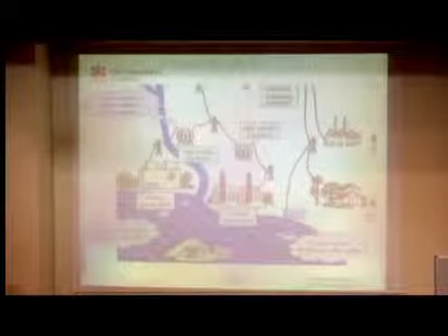So if we look at the top left of that, you can see that generator winding could be an epoxy nanocomposite, and of course the primary substation could be the same. We could on the pylons be using silicone elastomers with nanocomposites. If we move down the bottom, we could see that the DC cable insulation might be polyethylene. It might be polyethylene with a co-polymer with a nanocomposite. And looking down the right, we've got various motors which could have enamelled wire with nanocomposites on.